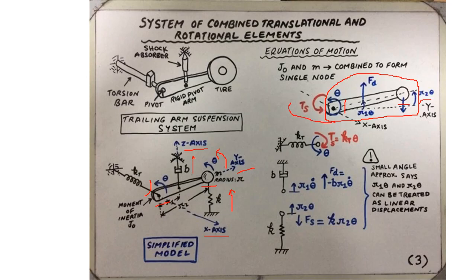If we draw a free body diagram of the torsion spring, there is a counterclockwise rotation theta. So this is a side view of the rotational torsion spring, where the angular displacement used to describe the motion is in the counterclockwise direction. So in response, we can just say the spring is going to exert a clockwise torque, as shown here.